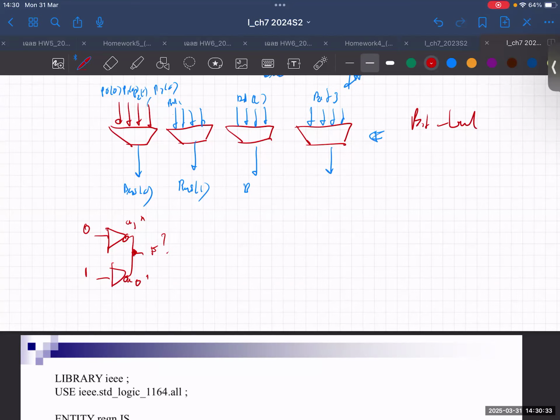But for a tri-state buffer, of course, you can do that, because you control the gates. Remember that? It's something like this. As long as you don't close the switches both at the same time, then you don't have problems. Unless you close them together and there is a conflict in the logic, then it's the same situation as this. So it's your responsibility to control and make sure that there are no collisions, right? Okay.